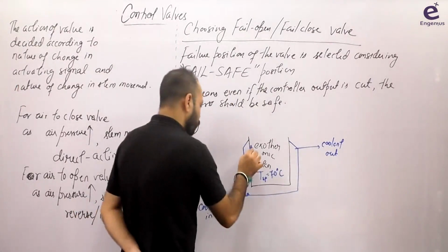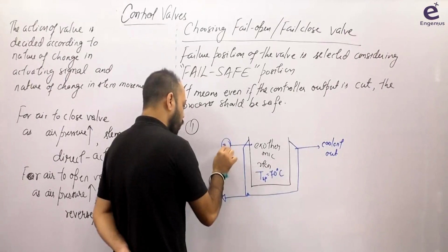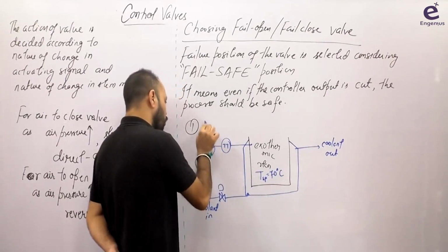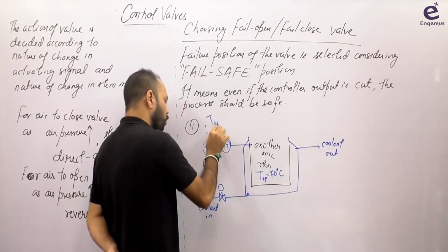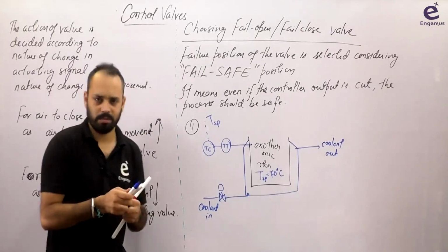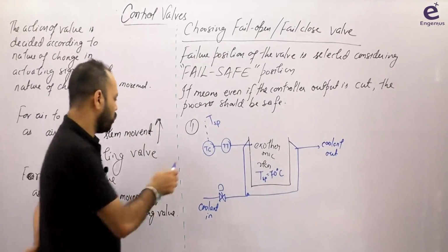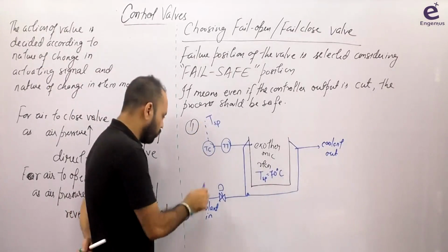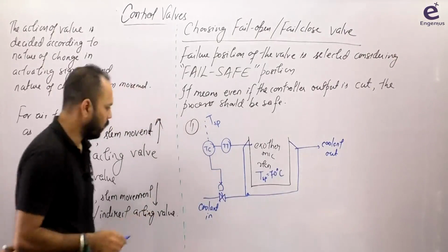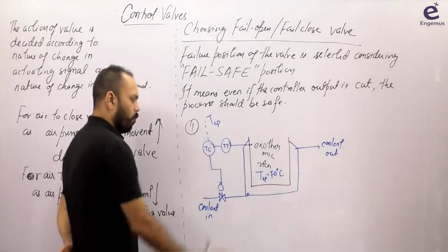Okay, let us make the loop. There will be a temperature transmitter, there will be a temperature controller. तो this controller, this is a feedback control. इतना तो आपको आना चाहिए. एक बार इंटरव्यू में डायग्राम बनवाया गया था मुझसे, है ना? इतना आना चाहिए आपको, that you can make a simple feedback control loop. Set point will be provided to this controller. This controller is going to adjust this valve flow rate, correct? This is the controller giving output to the valve, and this is the process.